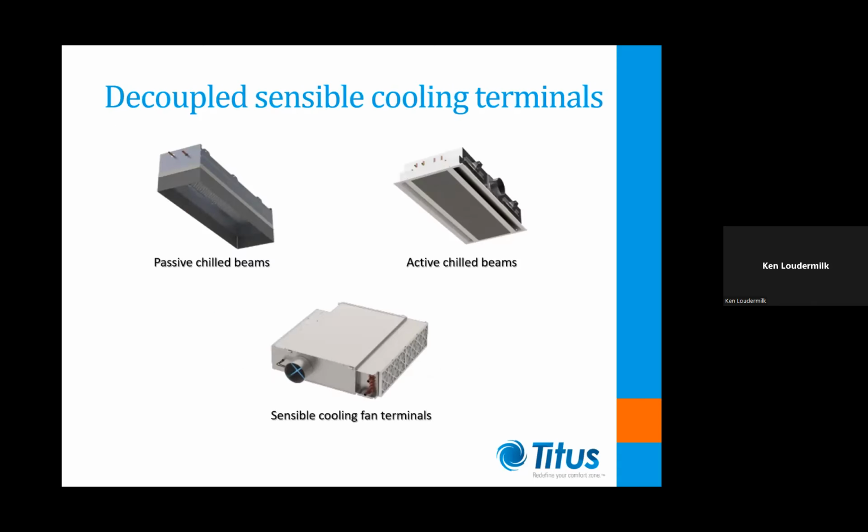As such, DOAS air handling units are commonly paired with zone terminal units that supplement the zone cooling demands. Air-water system terminal units are fitted with integral chilled water coils that perform most of the zone sensible cooling. These coils utilize chilled water delivered above the ambient air dew point and thus do not produce condensation nor contribute to the zone's latent cooling. The sensible cooling provided by these devices allows ducted airflow rates to be reduced to that which is required for zone latent cooling.